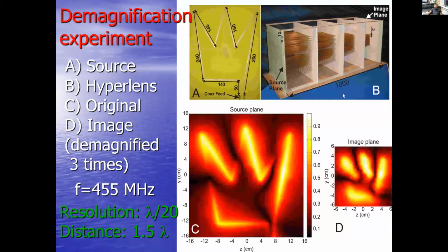The minor problem over here was that for scanners in microwaves, we usually should use plane interfaces. If you create these hyperlenses larger, then you cannot fulfill the Fabry-Perot resonance condition. So basically the length of the wires in the corner of the lens is no longer equal to the length of the wire in the center of the lens. And this is a problem. You're getting disturbances, you're getting Fabry-Perot resonance not everywhere in the lens, and other problems related to this.